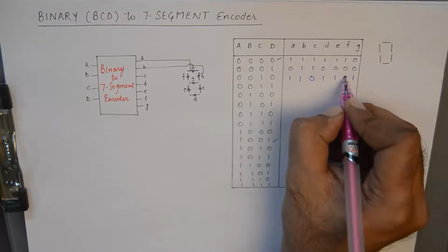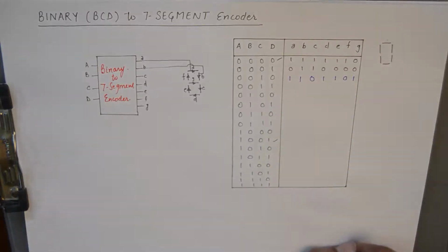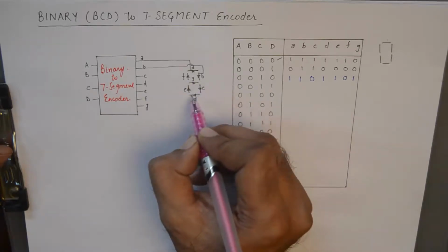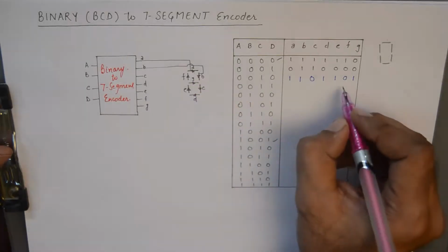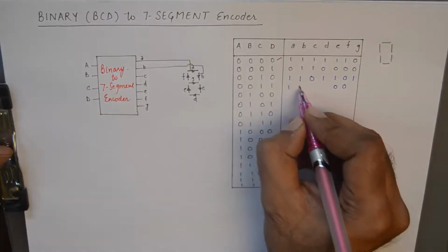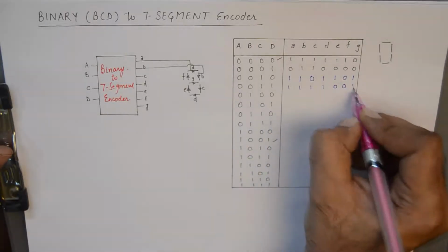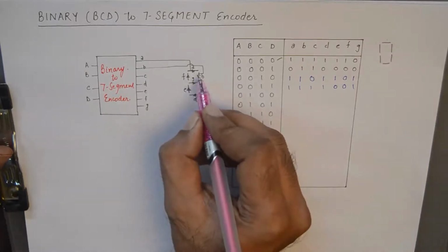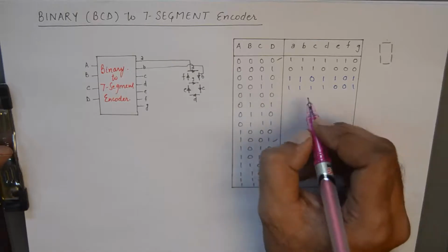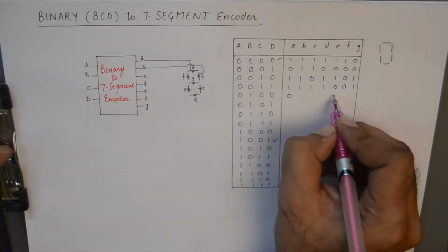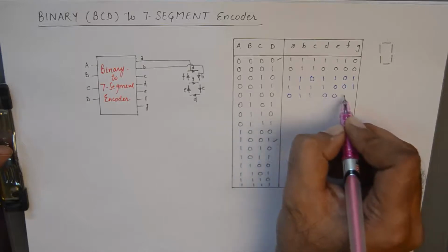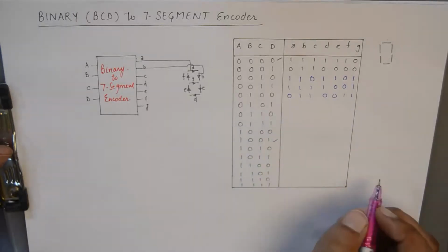So I put C and F as zeros. Similarly, 3 is lit up only when F and E are zeros. So 3 will be obtained by putting 1s here. 4 will be obtained when E, D and A are zeros. Rest everybody else is 1.